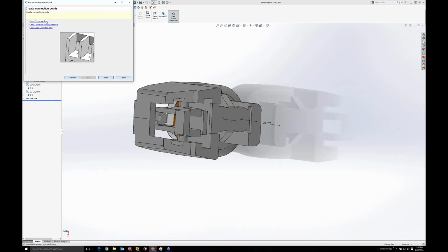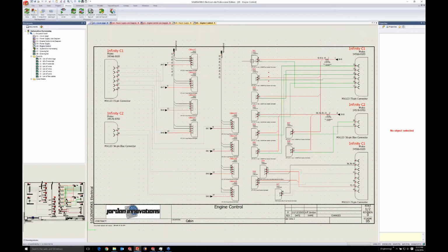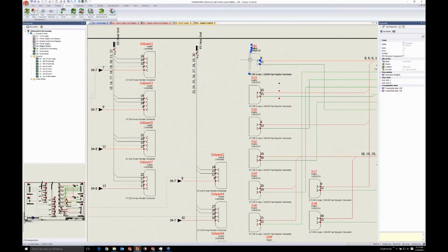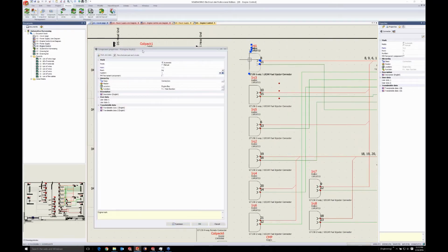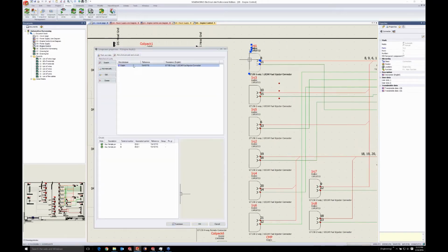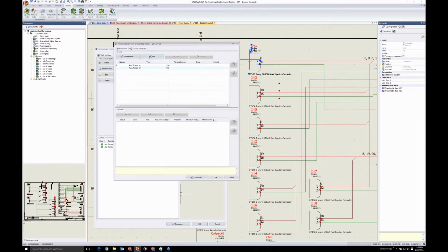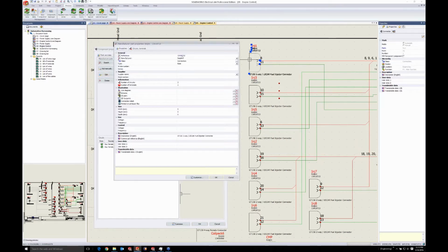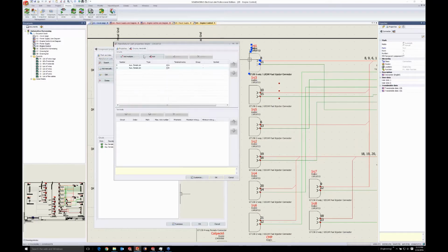This is where we can, if we know the circuit layout of these parts, and I'll flash back to SOLIDWORKS Electrical 2D here so we can actually see what I'm talking about. So this is my injector. If I double click it, I get its component properties. I hop in here to my manufacturer part information, and I can see that this is a Delphi 15419715. Great. My description, it's a US car fuel injector connector. It's GT150 series, two-way. Fantastic.